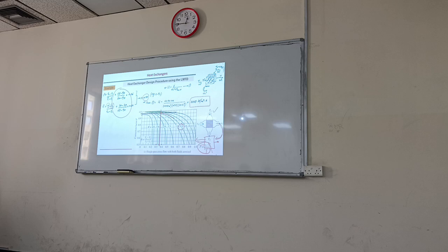Include the outer area, the whole heat transfer area, fin plus unfin, everything. Those should be given. No factors for the area. Just the simple heat transfer area, wherever the air comes in contact. Yeah, total area. But the equation will be Q is equal to UOAO delta T.